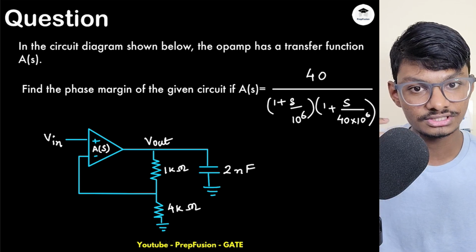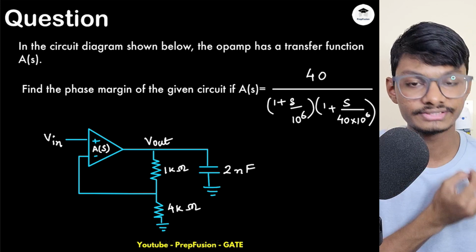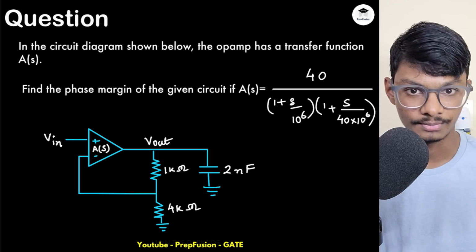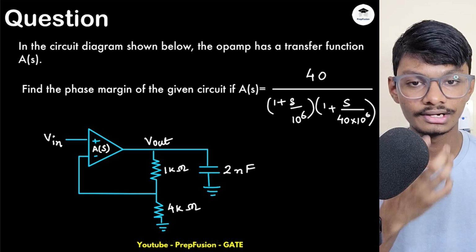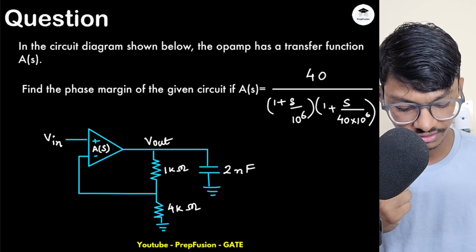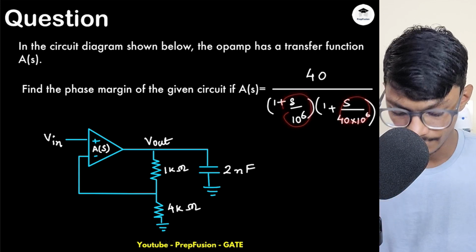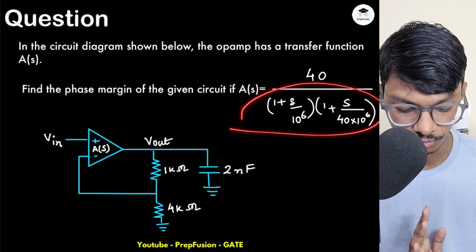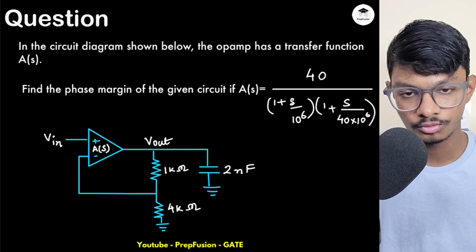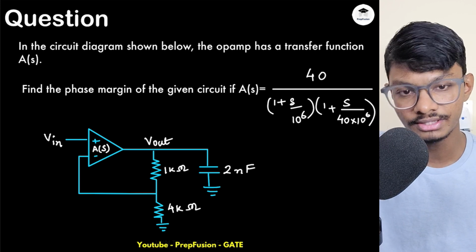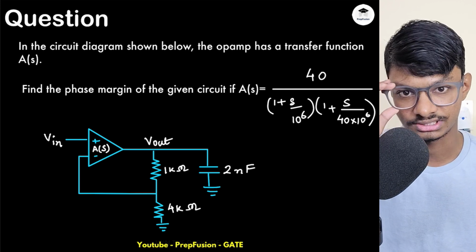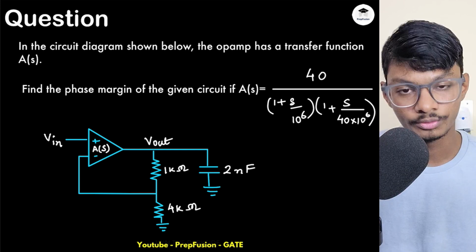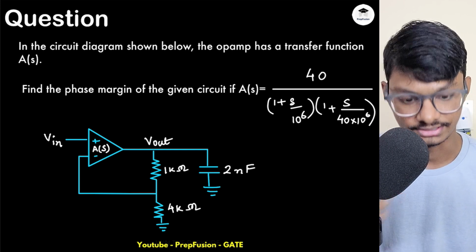So if you want to make the system more stable, what do these relative stability parameters mean? Gain margin and phase margin. Basically, they mean that if there is some variation in my poles, okay, currently what you're seeing are not the closed loop poles, these are the open loop poles. My closed loop poles will be something else, and that will tell me the exact stability, right? I'm just now doing the relative stability analysis.